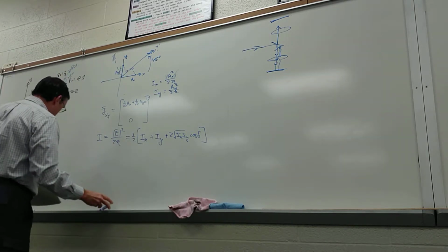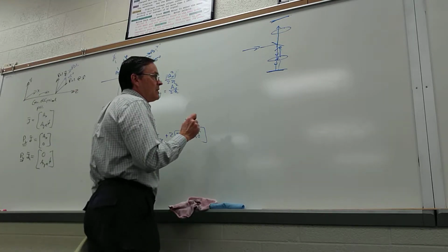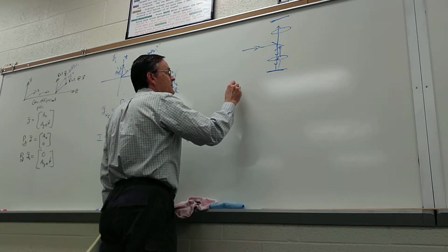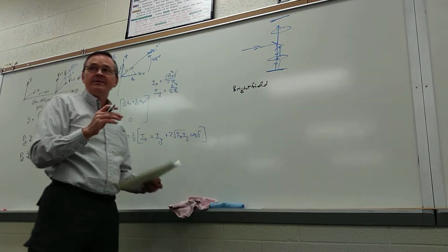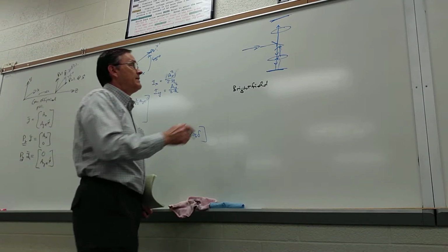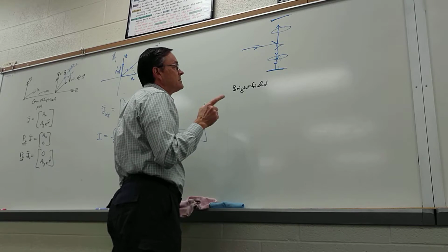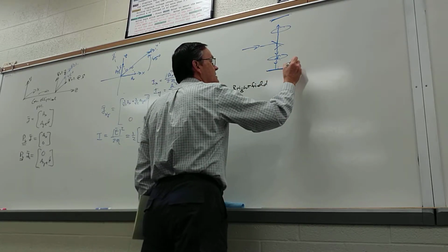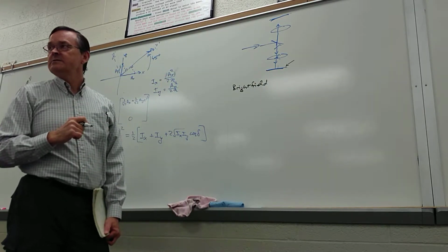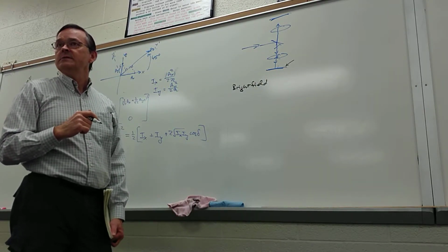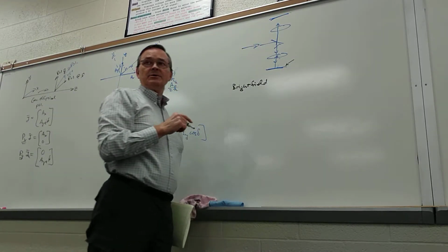So there are different ways in which we can operate a microscope. The way that you're all familiar with is called bright field. For the bright field operational mode, this is the setup. Basically any variation in reflectance on that surface shows up as a variation in intensity at the image.